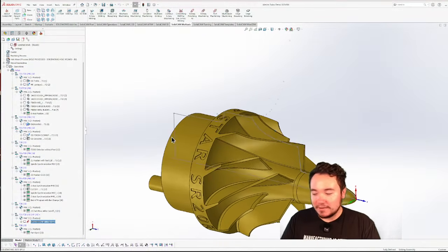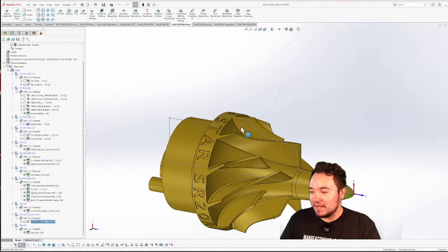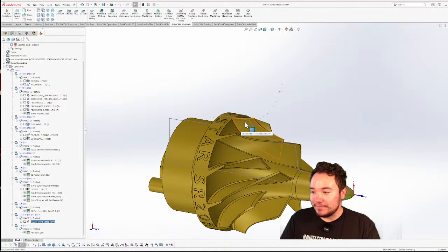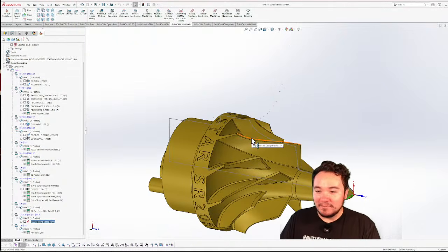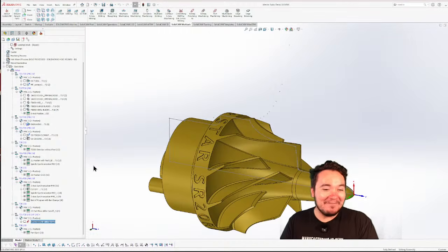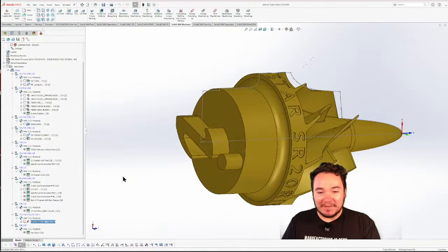The one of choice is definitely probably going to be the lollipop. But again, this is just a show part. And you get to see probably a lot more of the B-axis rotation with a ball end mill because it's trying to stay away from gouging it. With the lollipop, you could just send it in there and almost do just a 3-axis toolpath because there's so much clearance around that ball. But again, just a show part, not a production part.